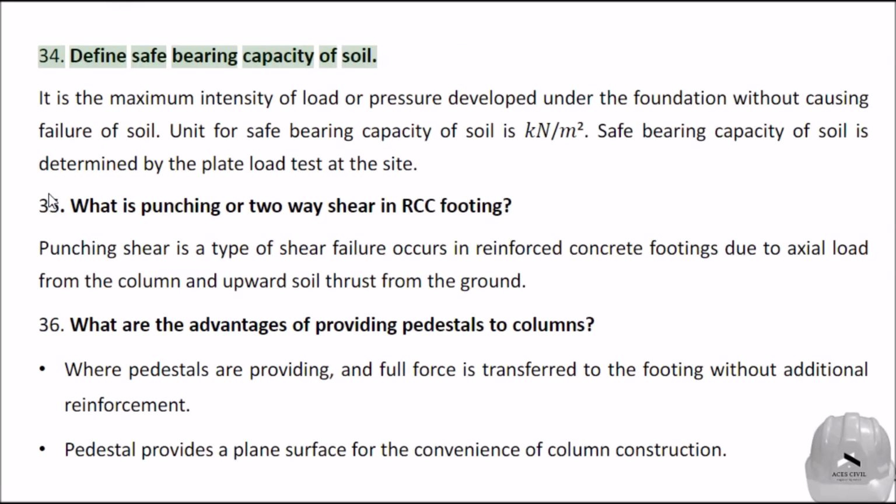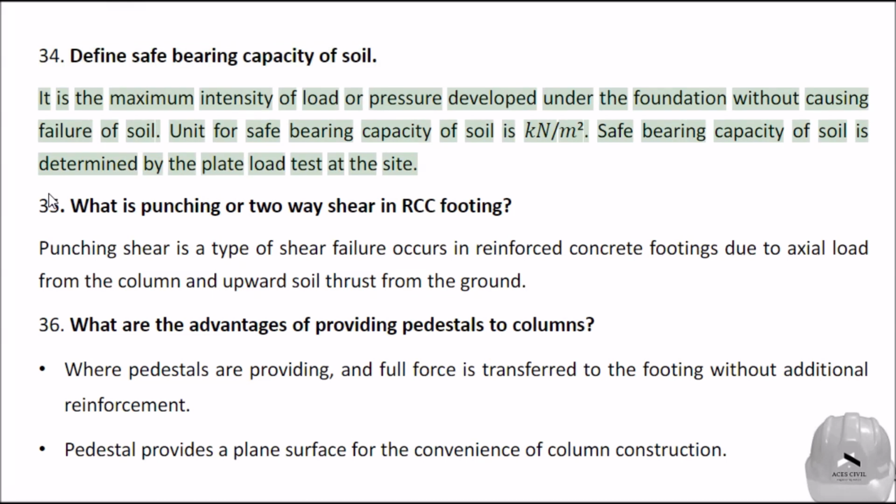Define safe bearing capacity of soil. It is the maximum intensity of load or pressure developed under the foundation without causing failure of soil. Unit for safe bearing capacity of soil is kN/m². Safe bearing capacity of soil is determined by the plate load test at the site.